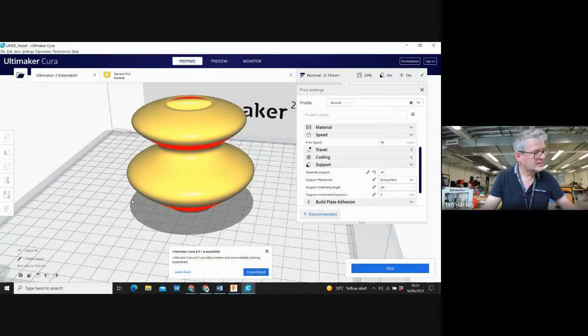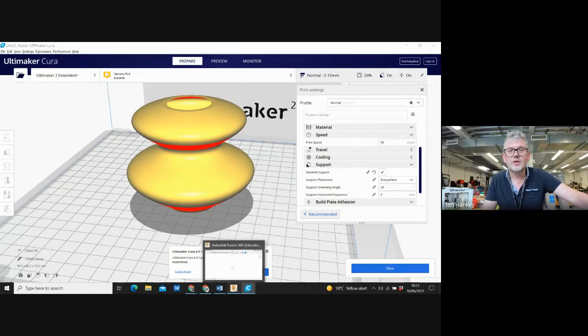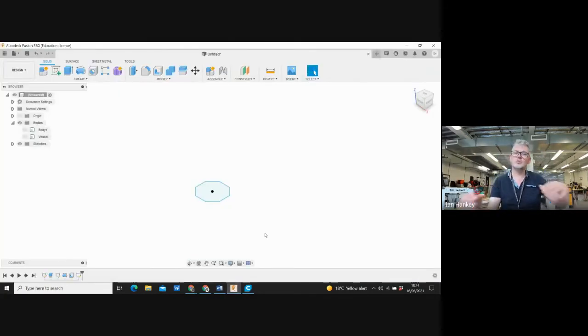Cool, that's great. Okay, so we've got another 20 minutes. So what I'd like to do is go back to Fusion quickly. And I was just going to show this idea of, if I wanted to put another sketch on this plane, that's no problem. I could put sketches all over this plane. What happens if you want to put a sketch somewhere above it? I'd like just to point out, if we go along the top from Create to Modify, Assemble, the next one is Construct. I'm going to left click on Construct.